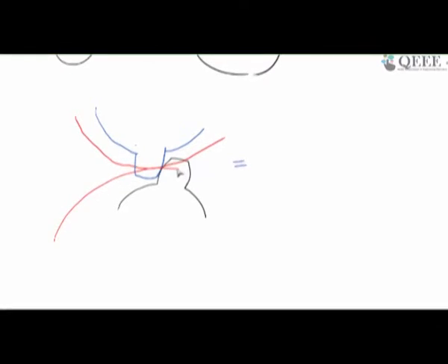So, we will try to contemplate that this motion transfer that is achieved through this gearing arrangement can be equivalently attained by two friction discs which are shown in this fashion. So, the radius associated with each of these friction discs is what is said to be the pitch circle radius.